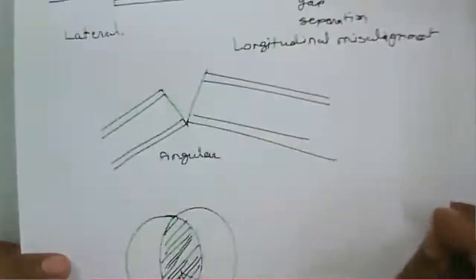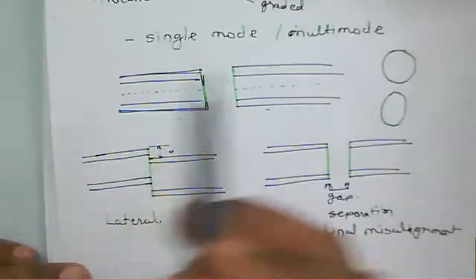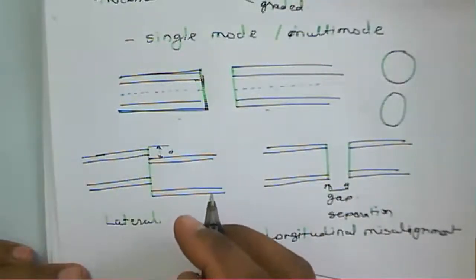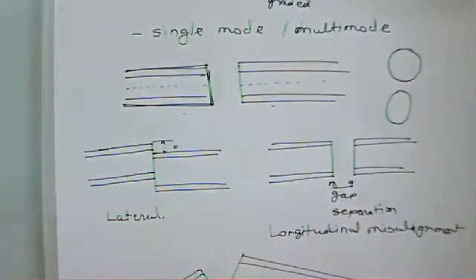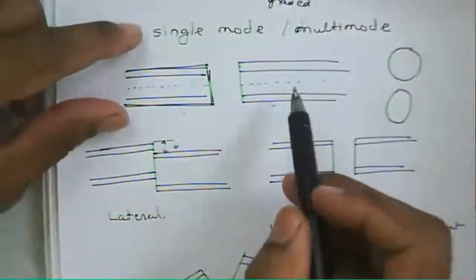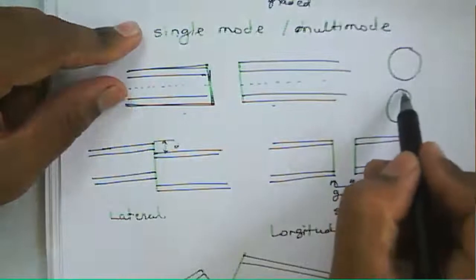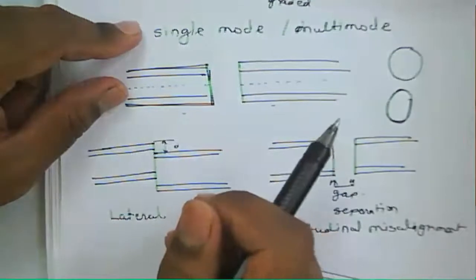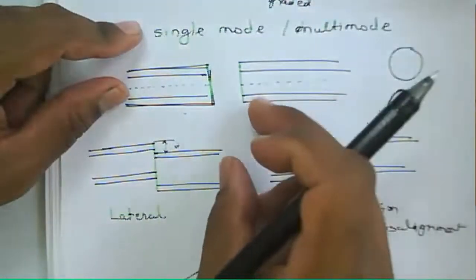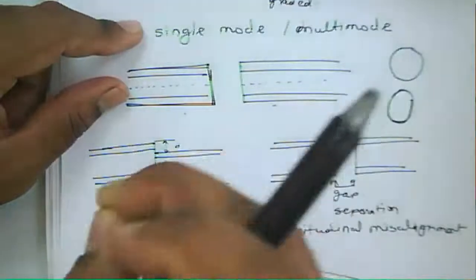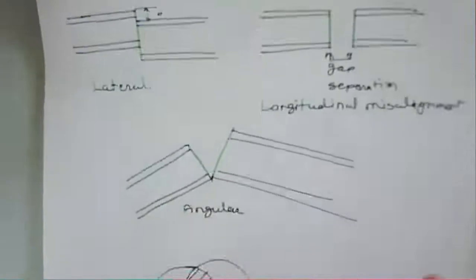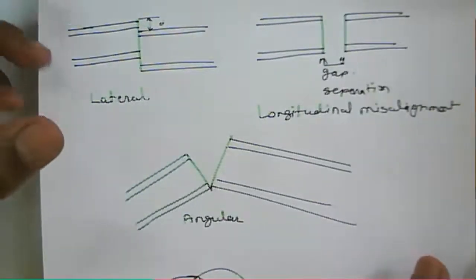So that is joining the fiber, but the fiber-related losses have to be considered, and then we can connect them. But all these losses, all these particular characteristics, occur at the time of manufacturing. So manufacturing variations, such as variation in the refractive index profile or the core ellipticity, mean we are not able to connect the two fibers properly.